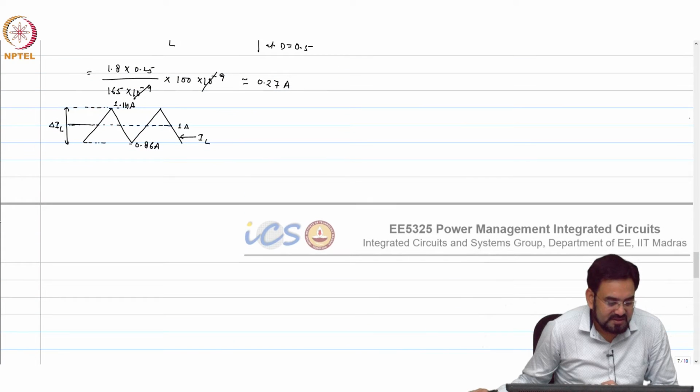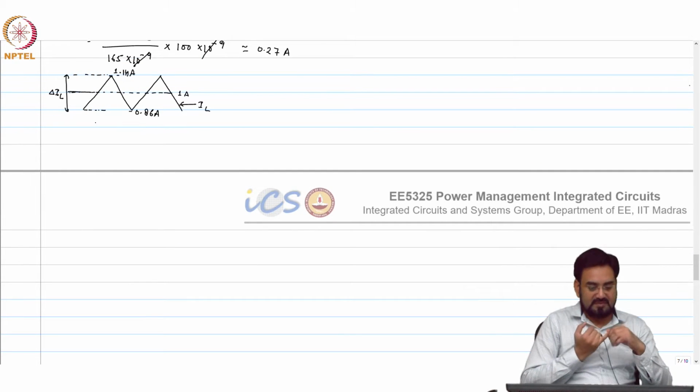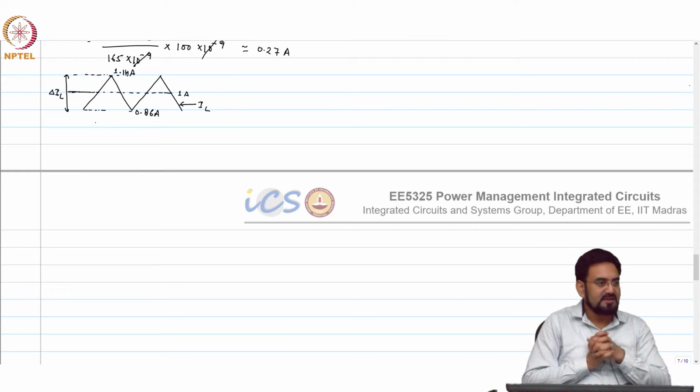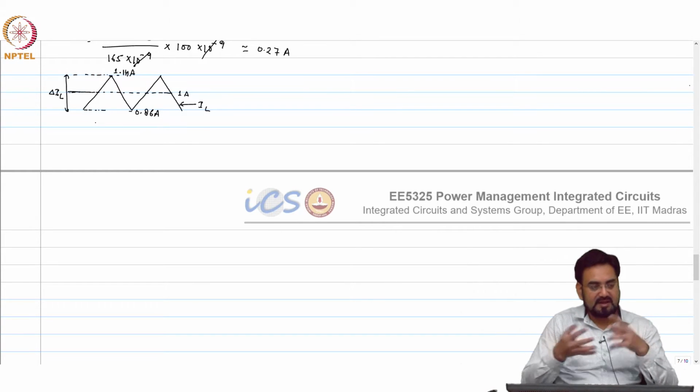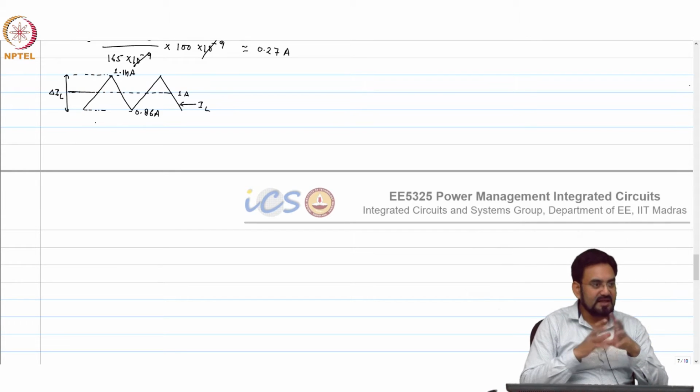So, which means the inductor should be able to support a minimum of 1.14 peak current. Okay. So, an inductor has two specs: RMS current and saturation current. When we say RMS, sometimes they call it I rated DC, and that is based on the temperature rise. ISAT, or saturated current, is based on the inductor's core saturation, and that will be the worst case. So, when your inductor is saturated, it is gone actually.